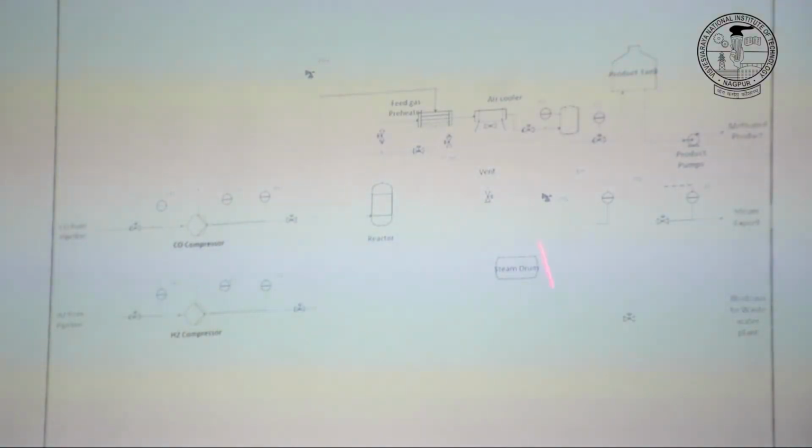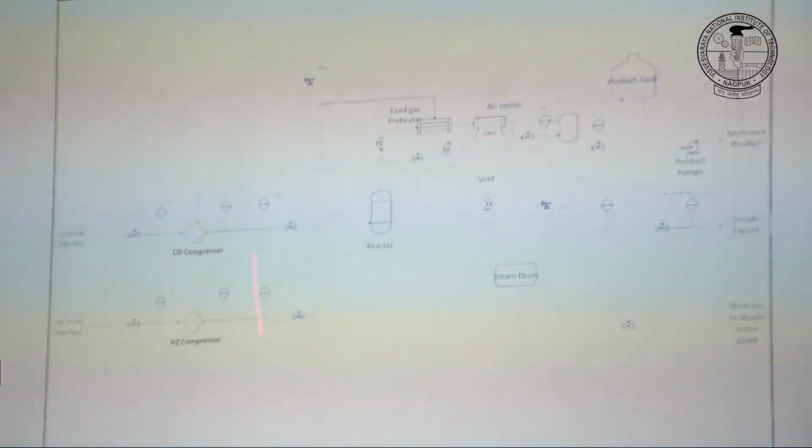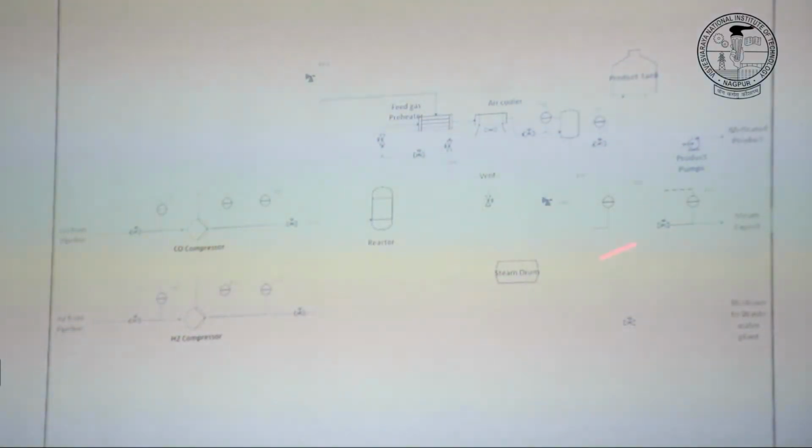What happens is that you want to have very clean water going to your jacket or your coil. There are so many chemicals that you add in your boiler feed water or steam system, right? And you could imagine you keep on adding something. It's once again the equation that Kanti showed: input minus output, plus generation minus consumption is equal to accumulation. You keep putting in these chemicals, and you are not taking out anything because it's a closed system, right? In steam there won't be anything. Steam will be pure water. You cannot vaporize these anti-fouling solid things, so they keep accumulating.